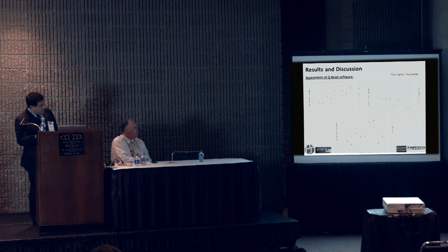So we see a trend based on the deviation of the bead width and the deviation of the weld reinforcement measured like that signal I told you. So they try to follow the same trend. Okay, you have some difference, but both the software and the weld engineers said that's the most beautiful bead that they found, number 6.